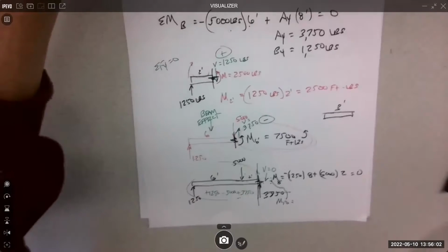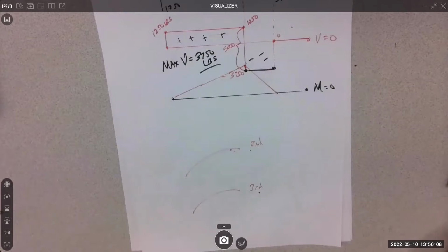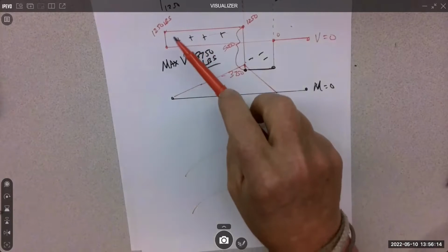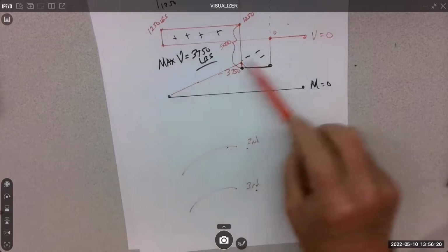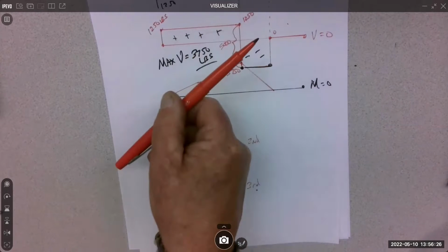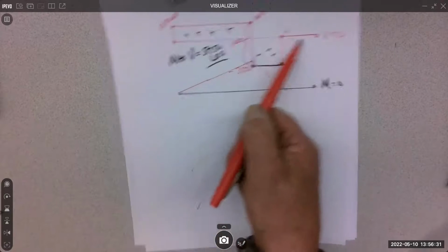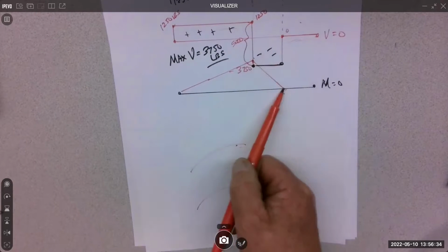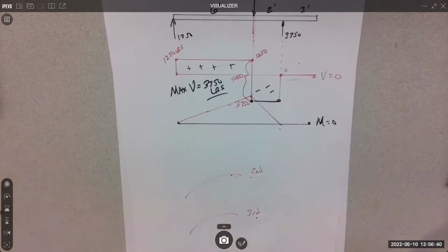All right, that was a lot. You're going to draw some shear diagrams, but honestly, I encourage you, if it looks simple, go for the moment diagram too, just trying to figure out these slope things. Like, oh, the sign of the shear gives me the slope. It has to be here. Notice I didn't worry about whether it's steep or not steep. I don't care. Just get it in the right way. And then look, it goes to 0. It goes negative, comes down to here, and then it's 0 out here. There's no shear out here, so there's no moment out there. So we just start to interpret these things and be able to draw these diagrams, right? That's kind of the beginning.